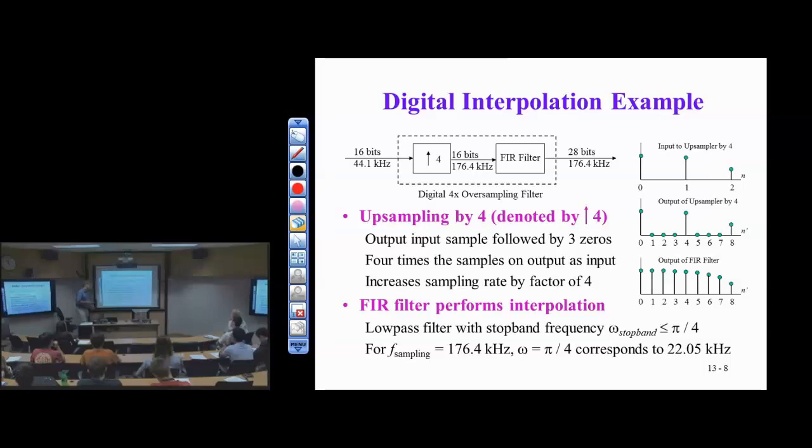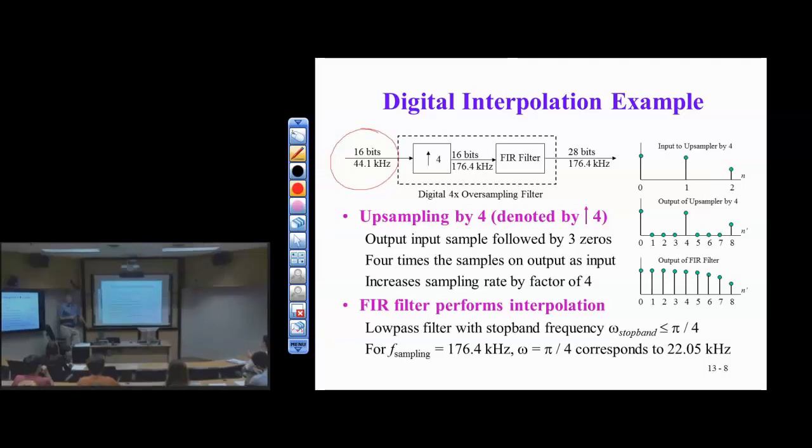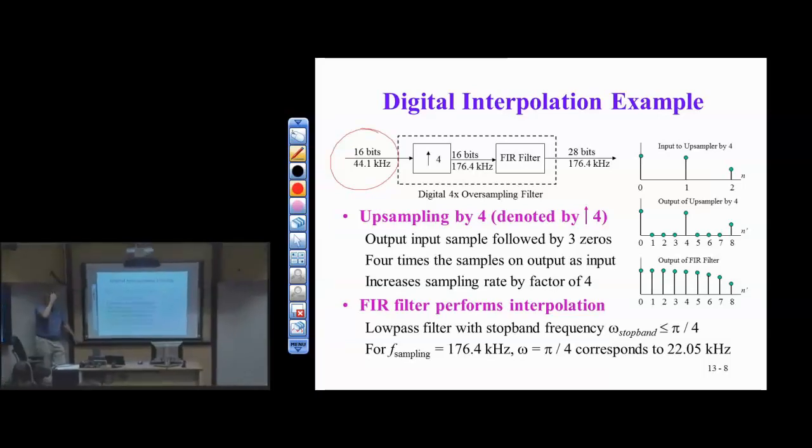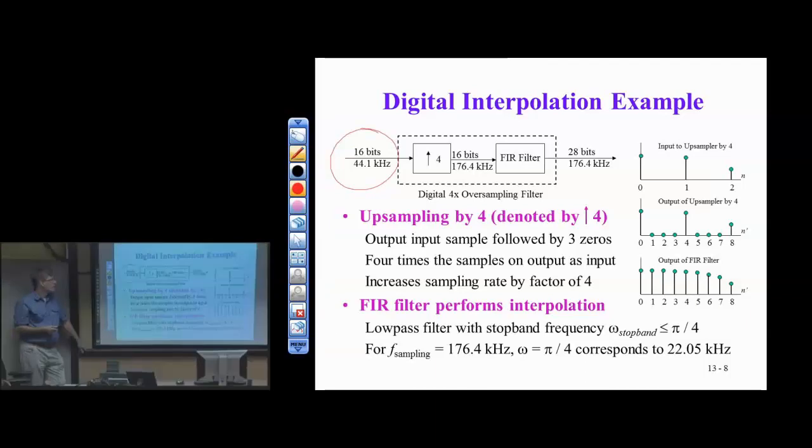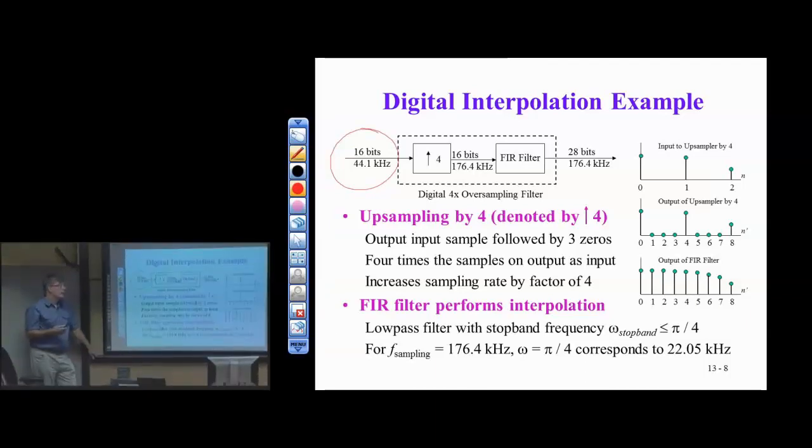So again, this is a general issue of discrete time interpolation, and one of the reasons we want to do this entirely in discrete time is that the alternative is to take our discrete time signal that we start with, in our case an audio CD signal, could be an uncompressed MP3 file. MP3 is actually MPEG-1 layer 3 audio, in case you're wondering, from 92 actually. It's a pretty useful but older standard. So we uncompress the MP3. A lot of those MP3s started life as an audio CD track at the standard 16 bits per sample and a sampling rate of 44.1 kilohertz. And in this demonstration, I just show you one channel of the audio, not both.